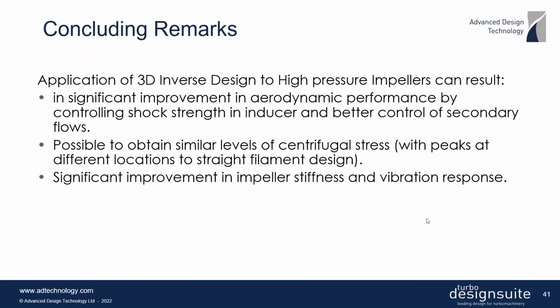So some concluding remarks on transonic impellers. So basically, by applying 3D inverse design, it's very easy to control shock strength in the inducer. And generally, we find that using aft-loaded distribution at the hub and the shroud gives you very good control over the shock strength. And then a key benefit of using inverse method is that you automatically get the optimum pitchwise location of the splitter blades across the span. And this helps you to get a better matching onto the splitter, and that also helps with the performance improvement.